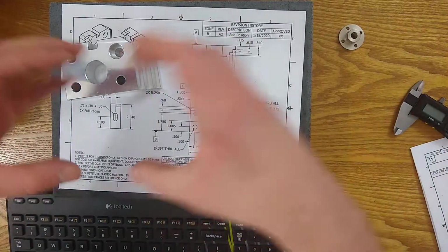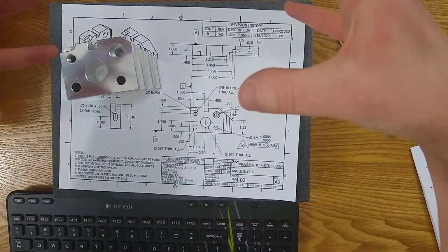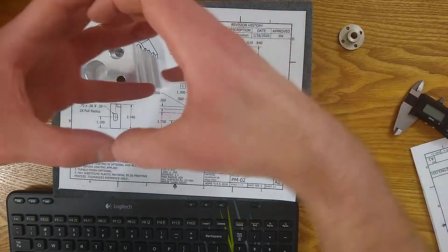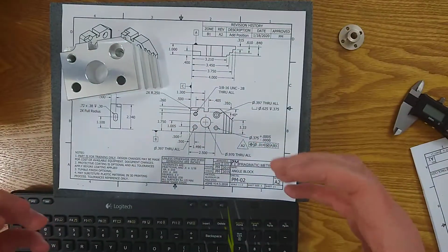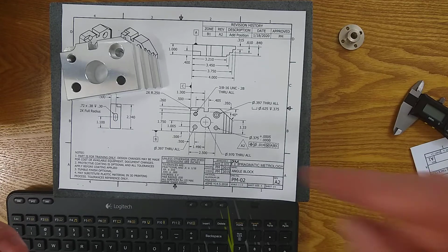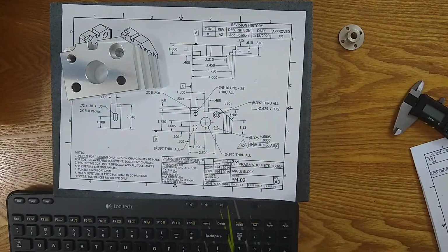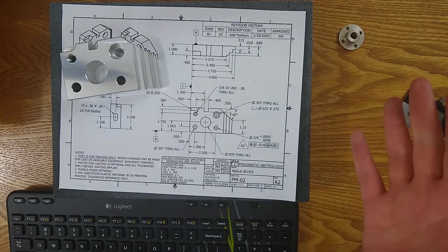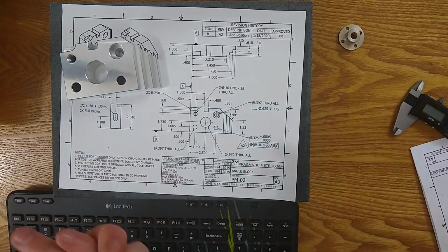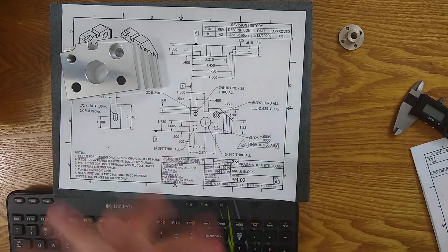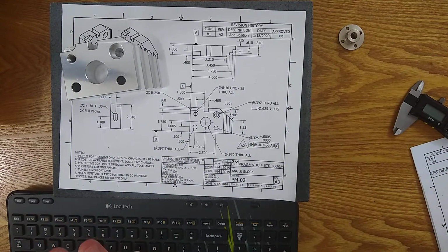So your holes are always going to be plus and your shafts are always going to be minus, so that you can definitely assemble. When you see it this way, you get a tolerance zone from it, and you have a new tolerance. That's all it is.